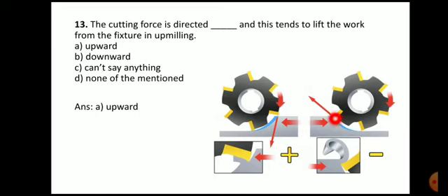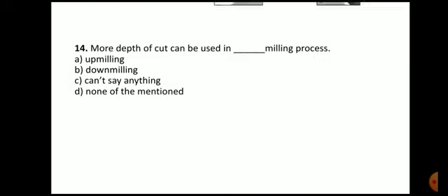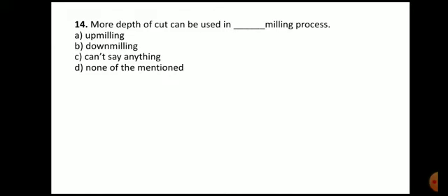As the cutting force direction is upward, it tries to lift the workpiece from the table. That is why heavy fixtures are required. So the answer is upward. The direction of cutting force is upward. Next question. More depth of cut can be used in blank milling process.